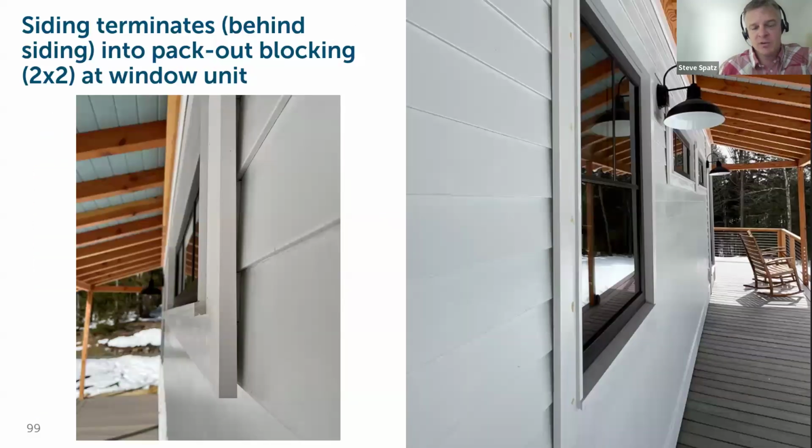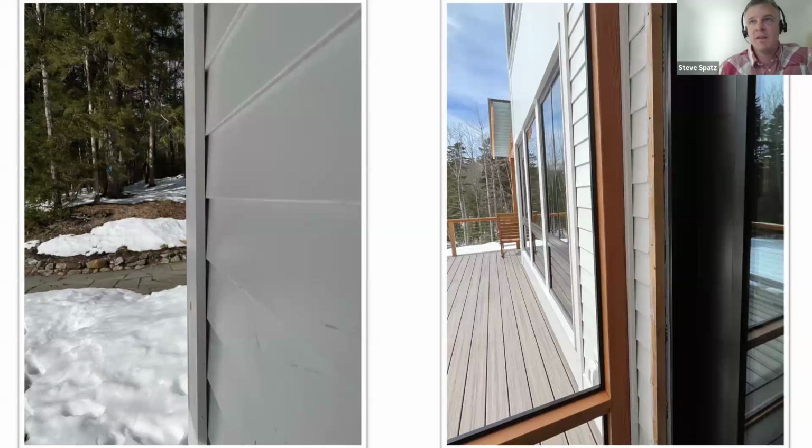And so when we look at some more traditional finishes, clapboard siding with traditional window trim, the ability of being able to put that siding behind the window casings and corner boards, no caulk anywhere at any of these assemblies. Any wind-driven rain that gets behind that siding or behind that window casing is going to drain out because of that 1x3 airspace, strapping space behind it. This also helps ease the installation of your siding too.